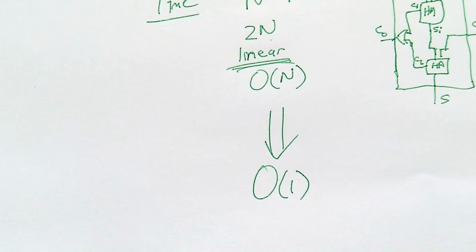It turns out logic design is one of the NP problems. So if we want to do good logic design, we go to things like Espresso, which are heuristics, rather than a fixed algorithm like Quine-McCluskey, because Quine-McCluskey can take two to the n to actually find that logic function. And it gets crazy, you know.